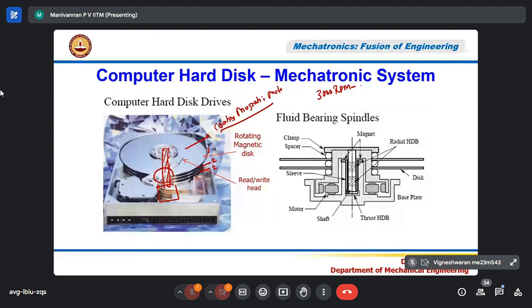But for a given hard disk, if you see the specification, its speed will be specified. The motor will run at constant speed without varying, plus or minus maybe less than 1 RPM, as close as possible. Accuracy of the rotation is very important. That is controlled by a motor controller. This motor is called a spindle motor, on which the discs are attached.